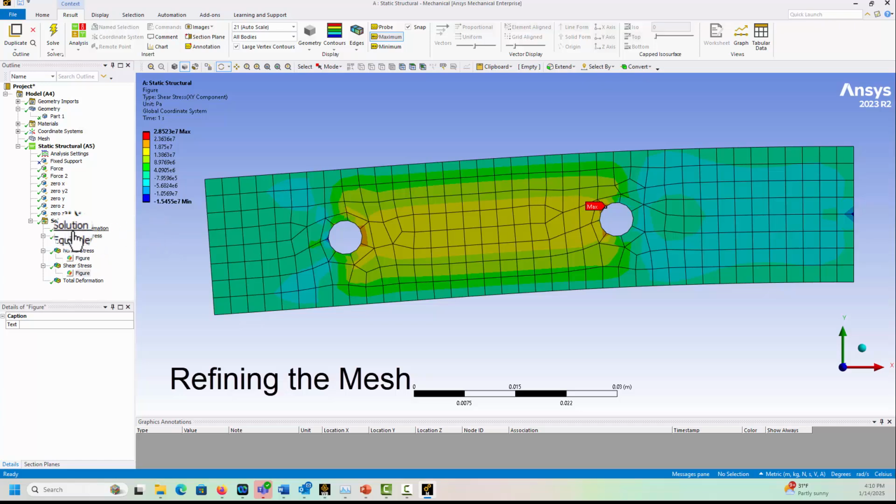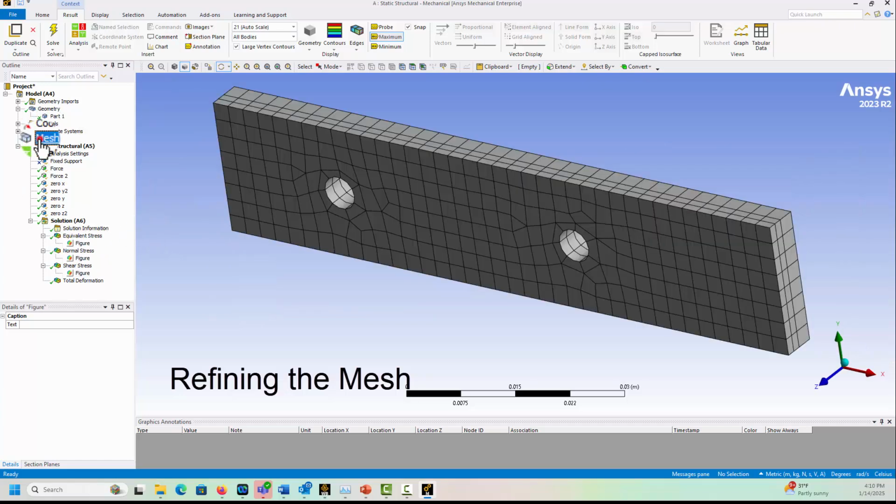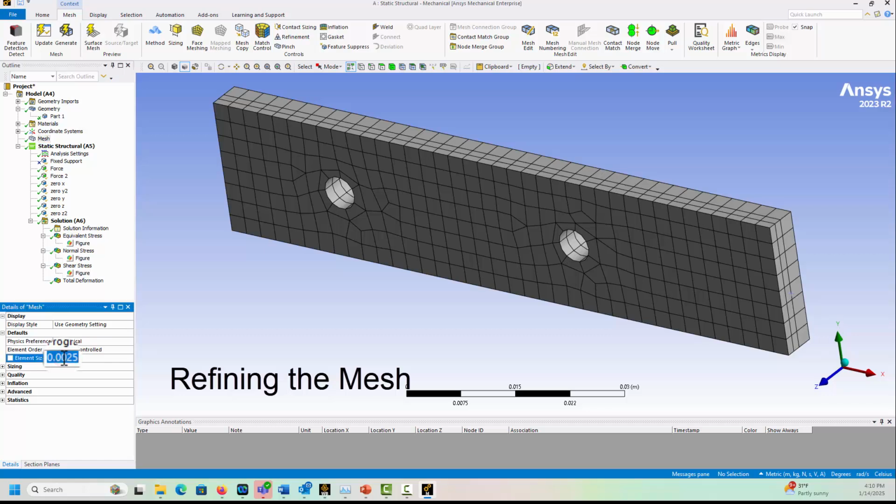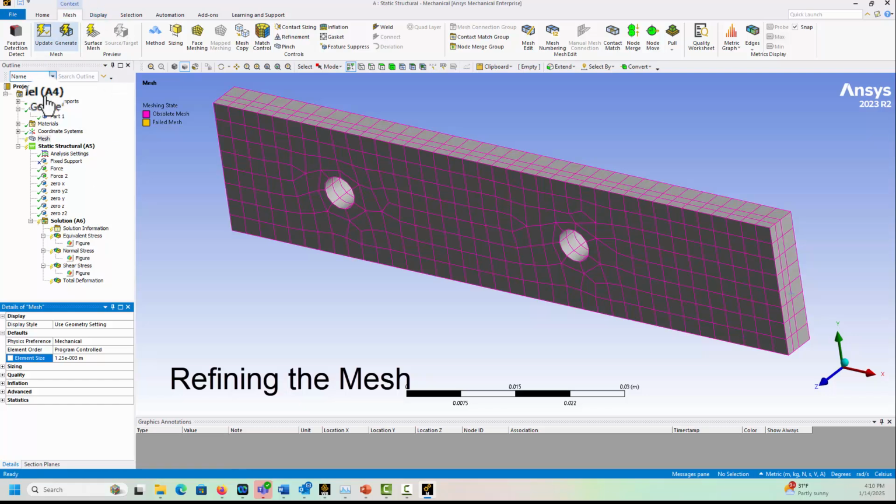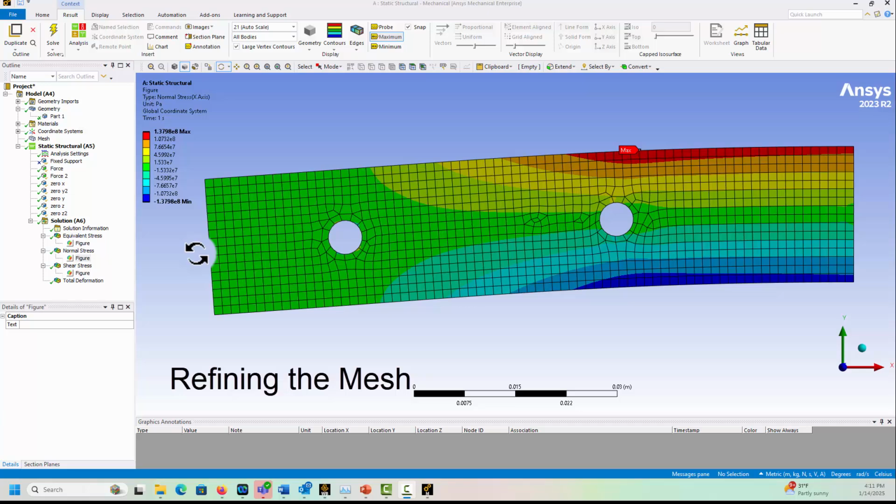Okay, so we've got those defined. Let's go back, change my mesh. I'll cut it in half, and we'll see how we're doing on our way to convergence. I'll solve that. Right, so that solved pretty well. And what we'll note here, I think I said it was 5 millimeters last time, but it was a 2.5 millimeter mesh, and I got 137.6. I refined that, cut the mesh size in half, and went to basically 138.0. That is plenty converged for the comparisons we want to do.